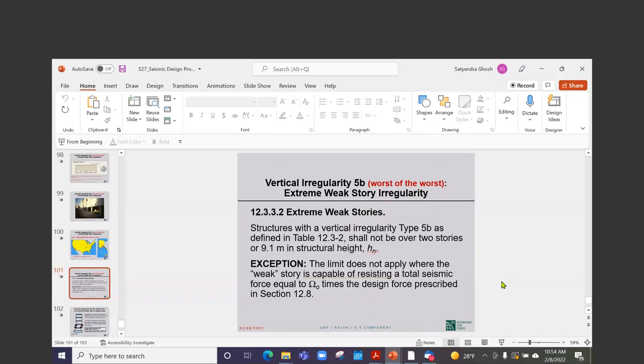There's one question related to seismic zone. He's saying that Gazipur is in seismic zone 3, but why is the seismic zone coefficient 0.2 in Table 6.2.15 for Gazipur?